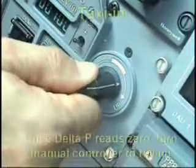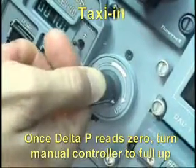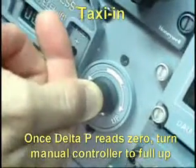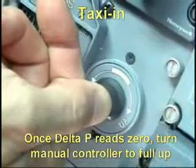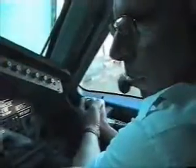Once delta P reads 0, turn the manual controller to the full up position. In this position, the outflow valve will be kept fully open, which will equalize outside and inside cabin pressure. After that, you can open the cockpit side windows and aircraft doors.